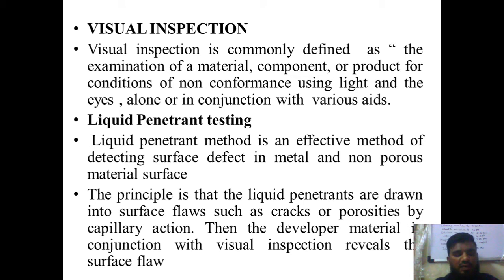Similarly, on a material, if there are any flaws and you apply some kind of liquid, so there are different types of liquid, we will see all those things next. When you apply some kind of liquid, where there are flaws or small cracks, the liquid will try to go inside, or it will create some kind of projections at that surface. Basing on that, we can understand that there is a flaw at that particular section.